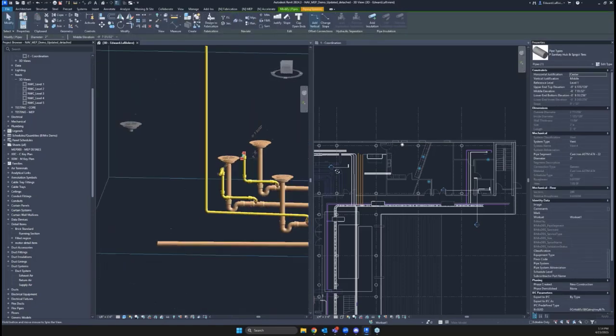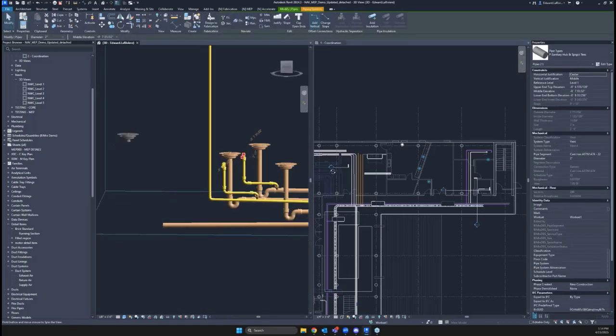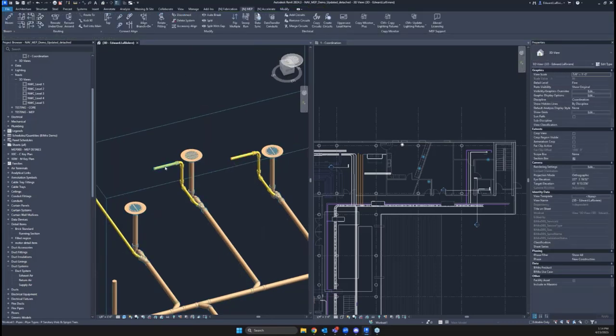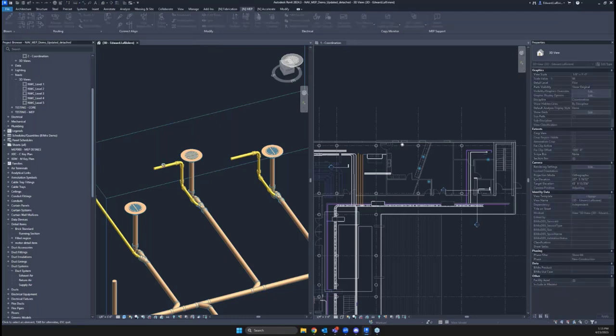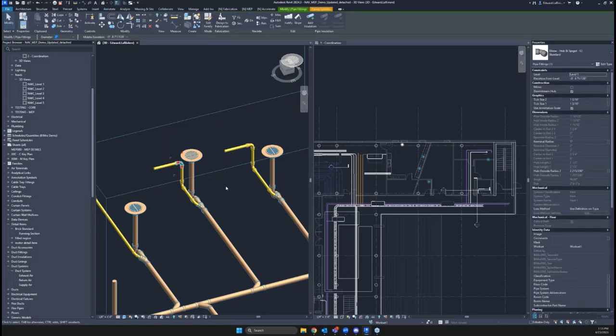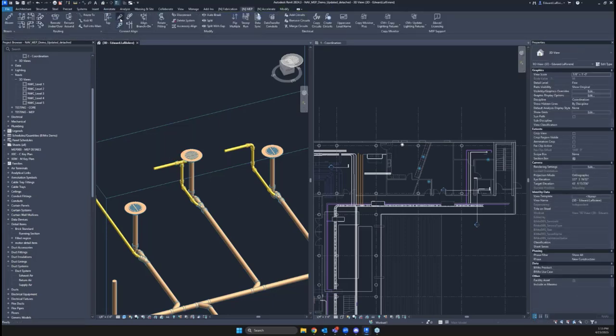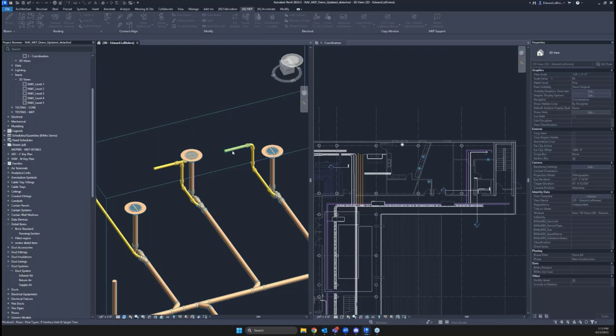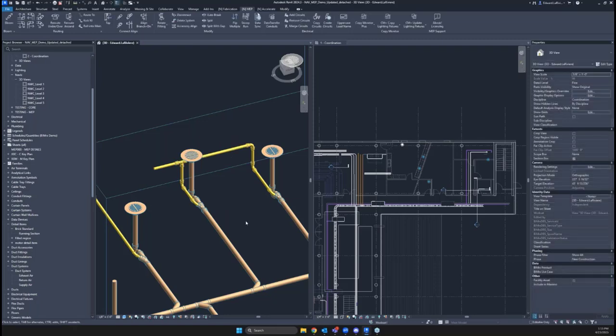If we look up here, I really need these things to be in alignment with each other. And you know what? Maybe I kind of want to line them all up against this back element. I could use something like Align in 3D to go ahead and get these aligned against each other. If we convert that to a T, we can use that same Move Connect because we just learned Move Connect on a straight extends into place.